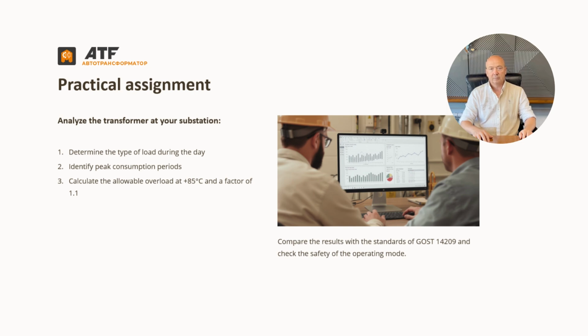Now let's apply this. Take a transformer from your substation or from your training manual. Answer 3 questions. What type of load does it handle throughout the day? Are there peaks? When do they occur? If the oil temperature reaches 85 degrees Celsius and the load factor is 1.1, how much can you increase the power? And for how long? Write down your answers, then compare them with the standard load duration tables. Is your current operating mode safe?